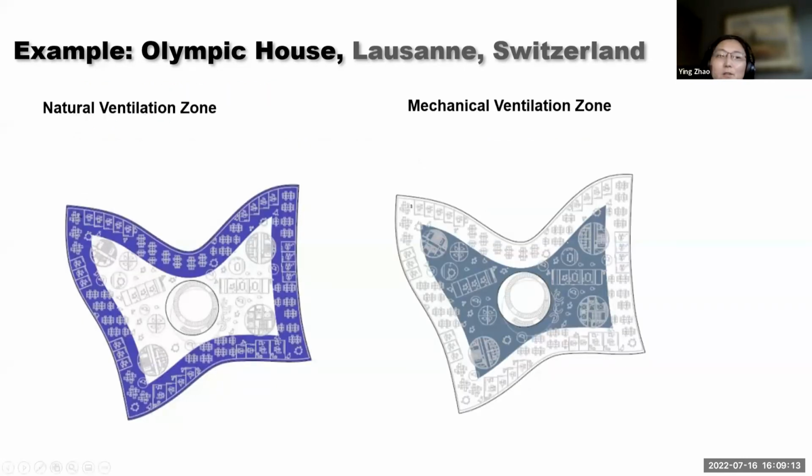For ventilation, the major concept is that the building is big in shape, not narrow and long. So the inside still needs mechanical ventilation, but they do consider natural ventilation at the perimeter zones. They designed the perimeter area so it can be shut off, while the internal central rooms are supplied with fresh air by mechanical ventilation.